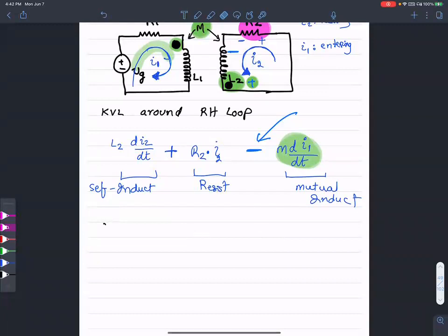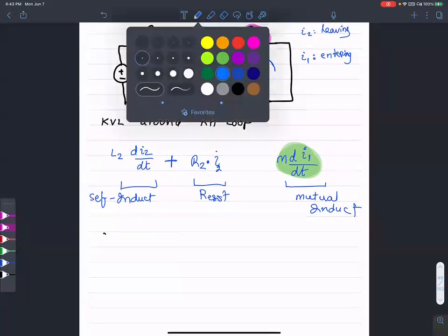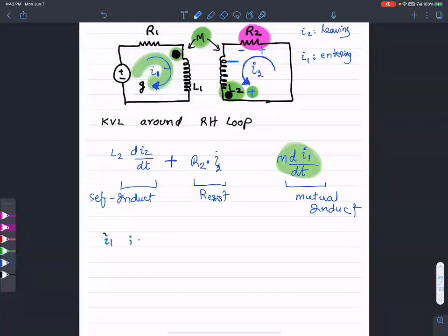There are a couple of things that we want to do here. The first thing is to notice the reference current. I1 is the current that is causing a voltage drop here, and it is entering. I1 is entering. Therefore, the L2 dot becomes positive at L2. That's not about the total voltage drop though, that's just about L2.